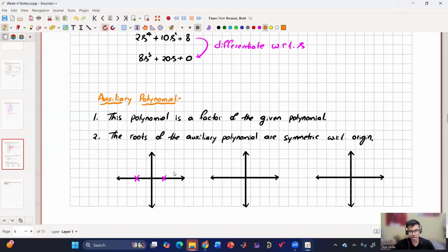So this is one case when the poles are real, then they're symmetric about the origin because it can be plus or minus 3, plus or minus 5. So one will be on the left side, one will be on the right side. Now if the poles are imaginary, say 2j, then it has to be symmetric. So it can be plus or minus 2j, plus or minus 4j. So it will be something like this. But what if it has plus or minus a plus jb? Then it can be a plus or minus something like this. So one on that side and one on this side. And if it happens in 4, then we'll have one more here and one more here. Basically, it is symmetric about the origin. That's what we want to say.